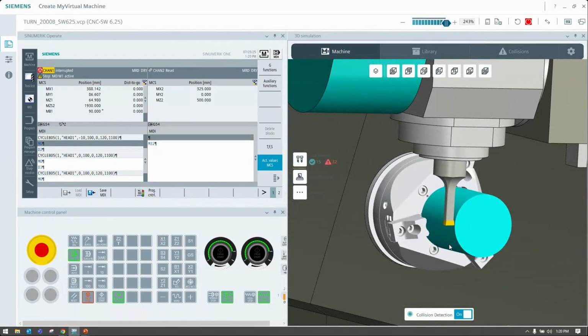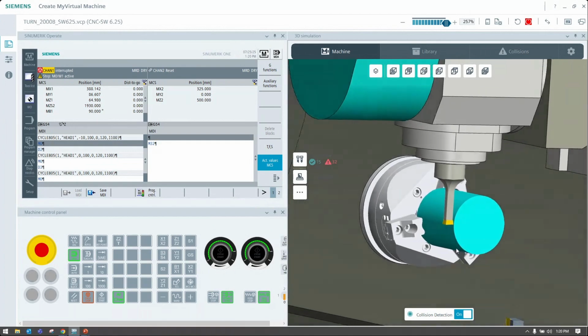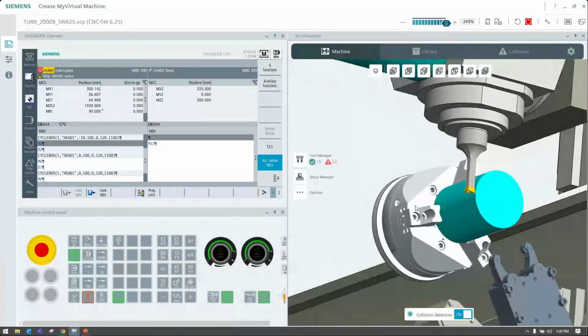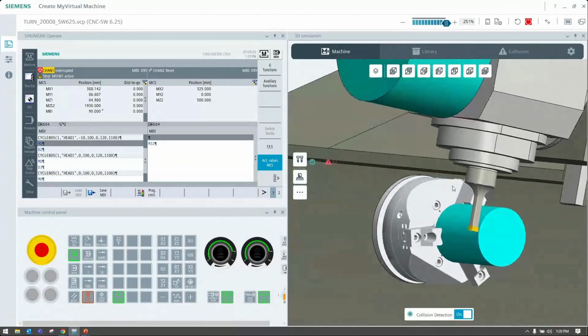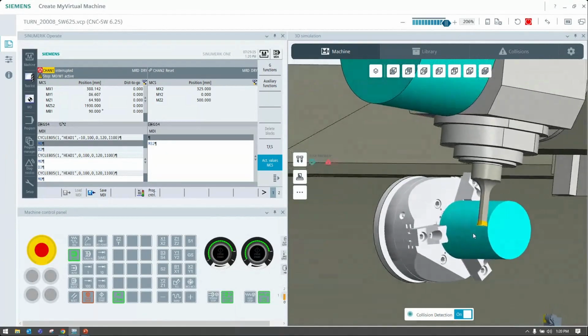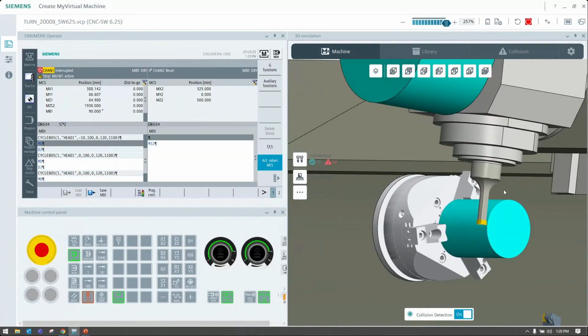Well, hold on. I think there's one thing that I just want to make sure everybody caught, which is actually pretty cool. Did you watch how the system is tracking that zero location? So as you change from a positive to a -10 degrees, the machine actually moved forward because it's maintaining that point. So that's really where this becomes kind of a game changer. When letting the control handle all this, we're allowing you to adapt that zero location to any orientation of that tool.